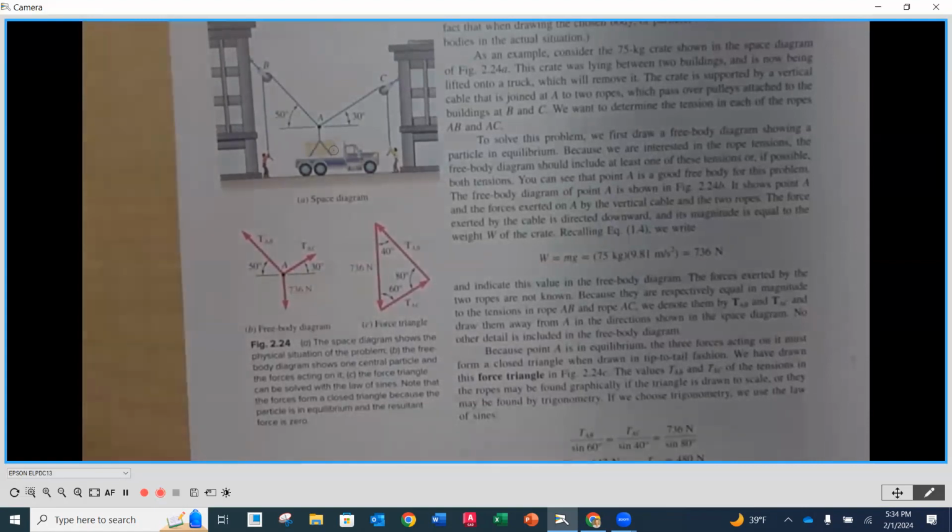Okay. So a typical problem here is going to be, now let's make a diagram of that. Well, what does that look like? Over here, down on the left-hand side, here's your free body diagram. We don't see the truck or the people pulling the cables, or the pulleys. We simplify our diagram and bring it down to, okay, what are the forces acting on each one of those cables? And then we represent those with the vectors and the labels that we see there.